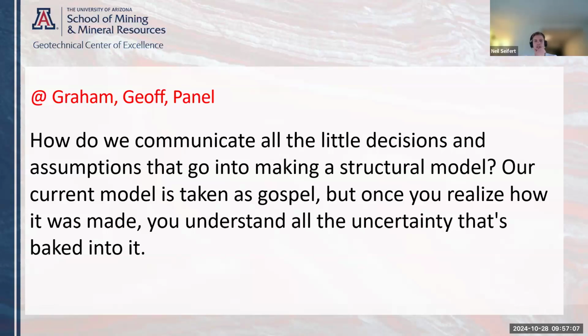Can I add one very small point to that too? I think we often communicate confidence in the model at the beginning when we hand over the model to the geotechnical engineers. I think we should also have a second step where the geotechnical engineer takes the structural model and does a slope stability analysis. After the fact, it would be great to have another meeting where the geotechnical engineer tells you what assumptions they made in their model, what their thought processes were, and how they evaluated your structural model. Because often I find it's in that meeting, that communication afterwards, where you're like, well, no, actually, that's not how I would have interpreted it, and you can communicate again.